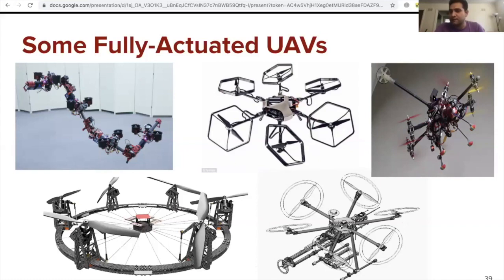I have been able to tilt it up to about 30 degrees, having full control over its roll, pitch and yaw. But more than that, because our tilt is fixed, you will not have enough vertical acceleration to overcome gravity. So it will fall. You cannot go completely to 90 degrees with this lower model, but with that one you can.